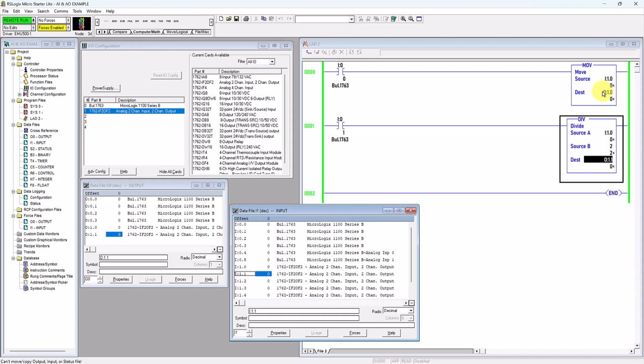So whatever you want the PLC to understand, to read, you have to convert it to the corresponding digital value. In other words, you have to give the valid input data range. So for this case, the valid input data range is 0 to 32760. You can get this range from the manual, and the manual can be downloaded from Google.